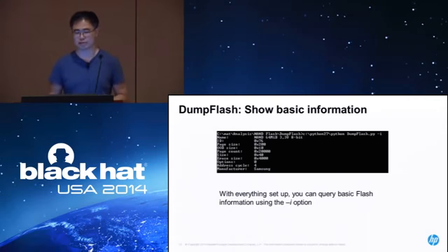So this one is actually opening the image file directly from IDA, because the first part of the image file is actually ARM instructions. They are first stage bootloaders. You can actually directly disassemble it, and this is ARM architecture. And make it code, it's jumping to this address, and then those are all those instructions. They are doing some really low-level initialization. It is really hard to understand, but still useful.